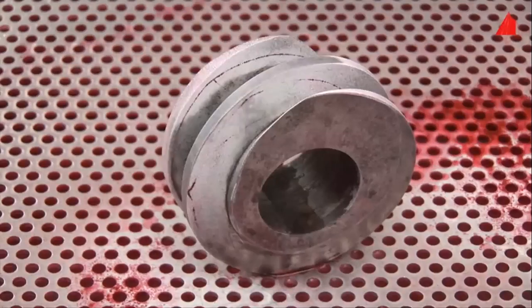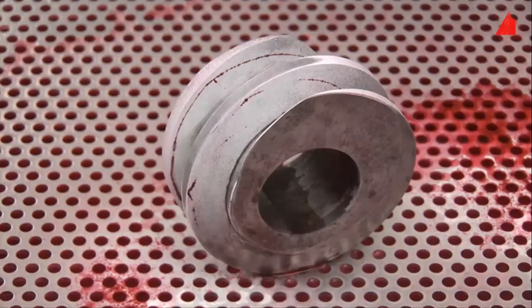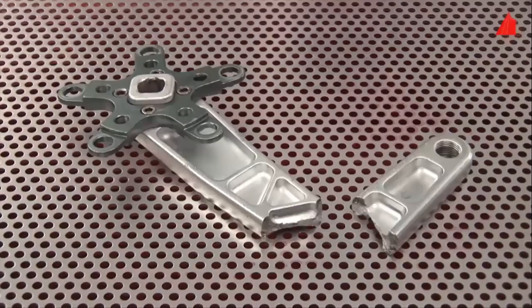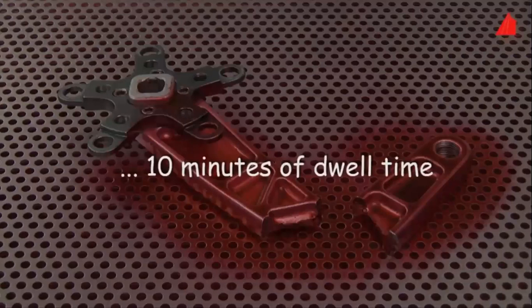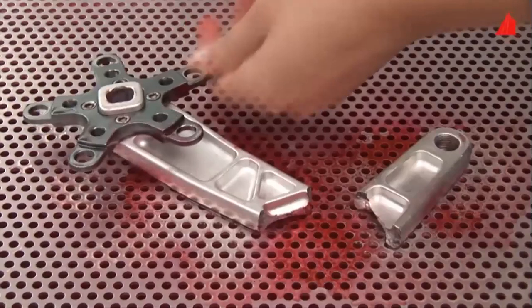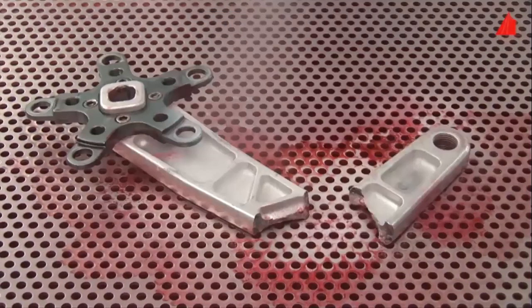That's it. Several cracks are indicated on the surface in deep red color. Okay, so these are the cracks. These dark red colors shown are the cracks present in the component. Next, the broken bicycle crank arm has to undergo the dye penetrant test. Spraying with penetrant, allowing to soak, rinsing, drying, and applying developer. Clearly, additional cracks are indicated on the fragments.